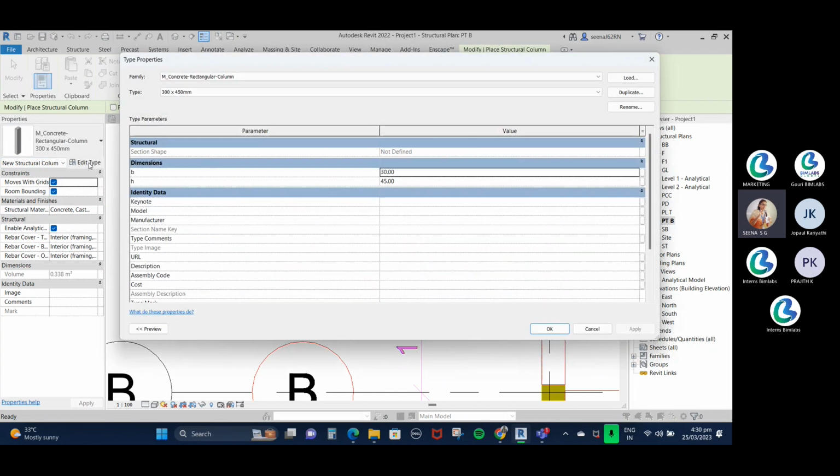In Revit, you have three different types of families. All the elements in Revit are families, but we can classify all the families into three main divisions. The first one is system families. Examples of system families in Revit are wall, floor, ceiling, stair. When I install this software, some of the types are already installed with the software. That is called a system family.